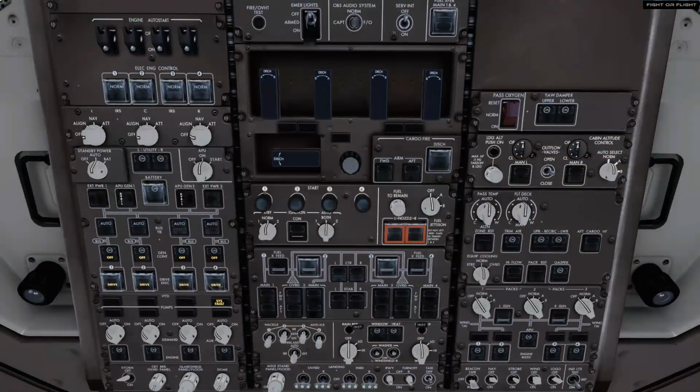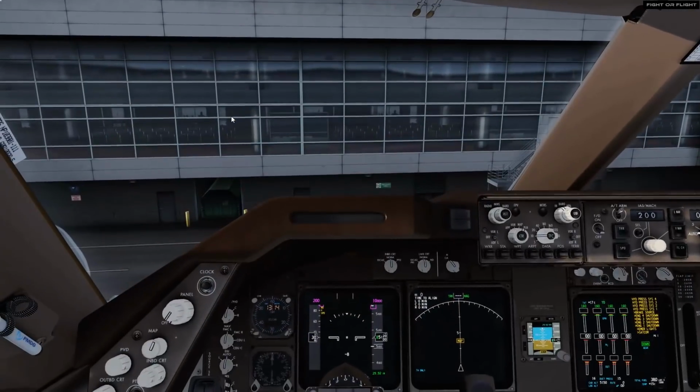When the avail lights come on, we can push the switches to select APU power. We'll turn the nav lights on to signal to the ground crew that the aircraft is powered up. Now we'll set all the IRS selectors to nav. The initial cockpit setup is now complete.